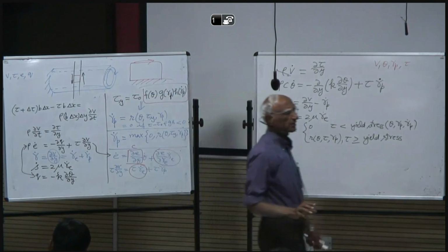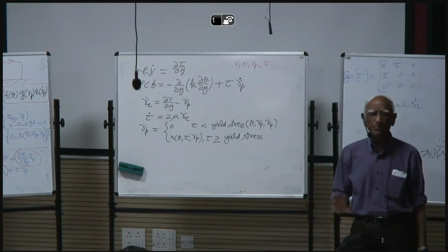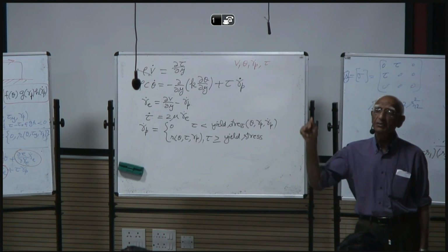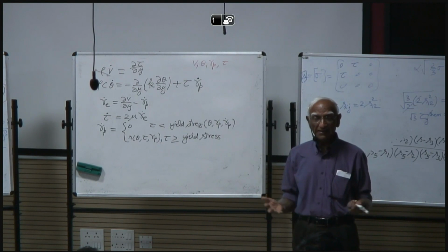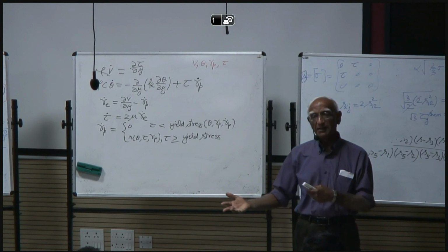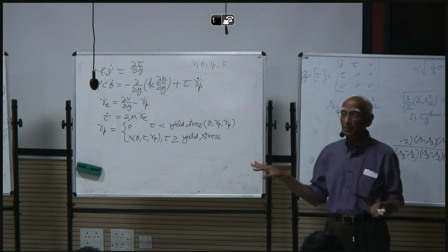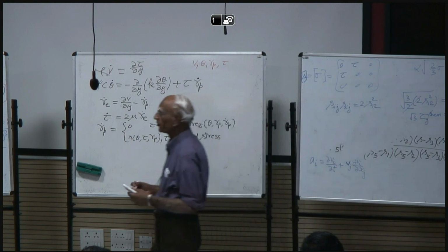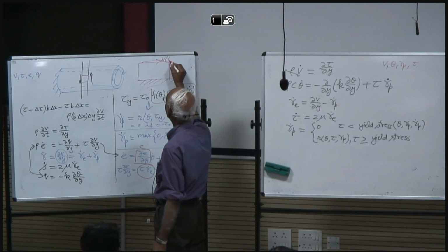Generally, if you prescribe load as a function of time, then it becomes harder to solve, because eventually the load starts decreasing as time increases, and there is no mechanism for us to decrease the load, because we cannot predict beforehand what the load should be. So the problems we solve, we prescribe the velocity here as a function of time on the top surface.